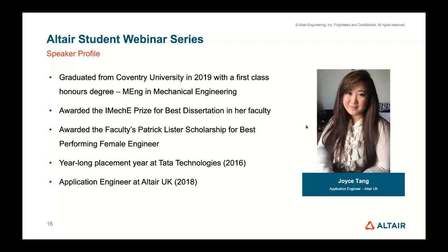So many more questions coming in. Can we simulate stress analysis of flexible bodies using contacts? When you want to incorporate your flex bodies, that will give you the stresses and strains that your part will go through during its time in motion. And you can also use contacts on it. There are macros in MotionView whereby you can put your flex body in contact with other bodies too.